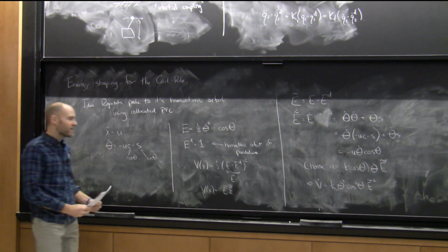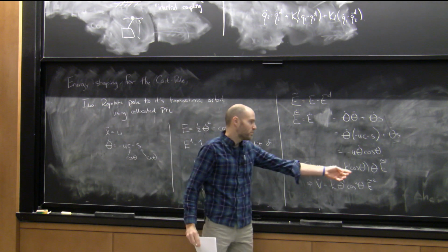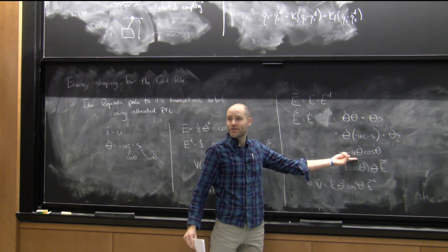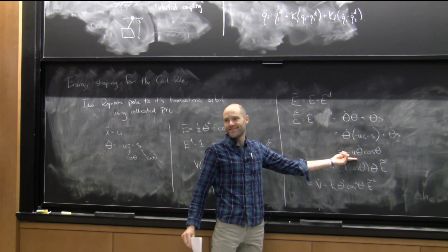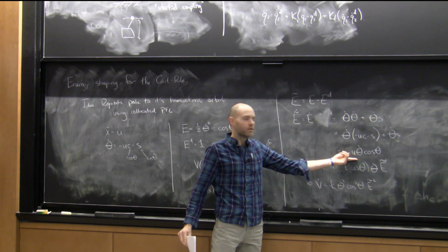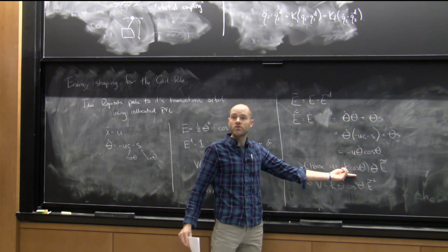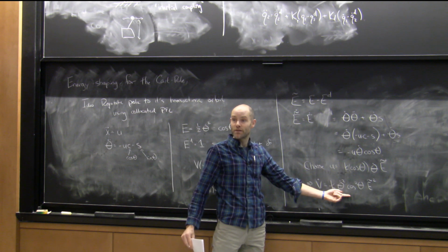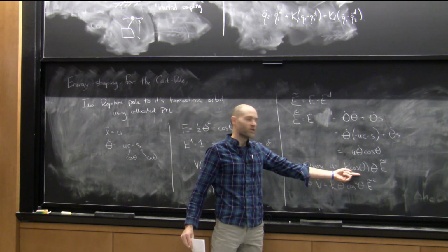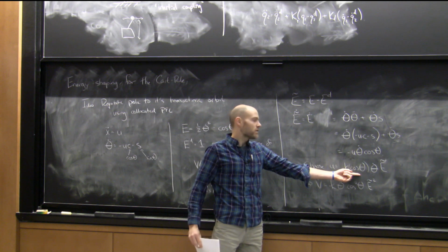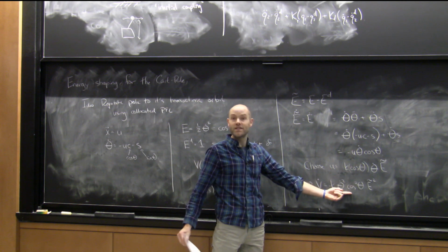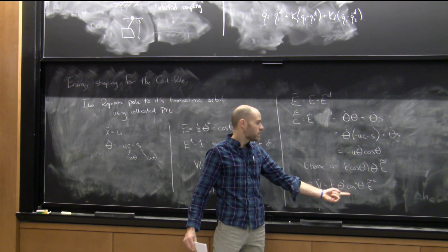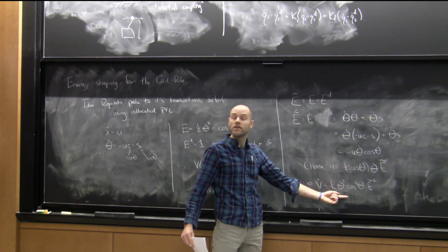There's an art to picking this, right? You could try to divide by cosine theta, for instance. That might be a bad choice, because that one does blow up, right? So there's an art to having controllers that not only achieve this goal of being negative in the Lyapunov function, but are also well conditioned for all theta, and don't depend sensitively on the parameters of the plant, like friction and other things that you don't know, right? So there's sort of this art that went on.